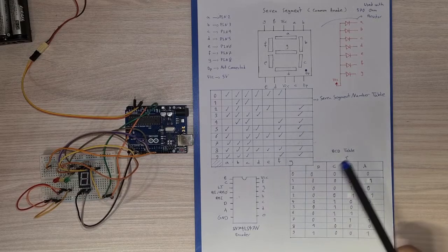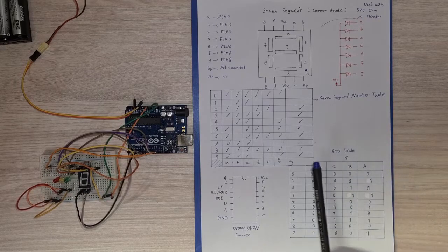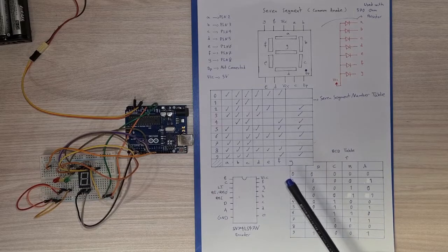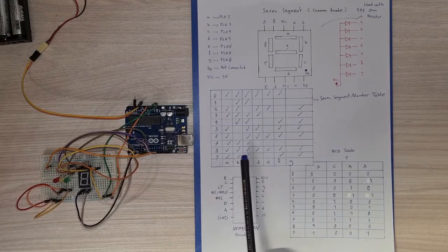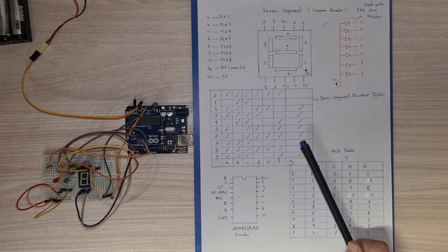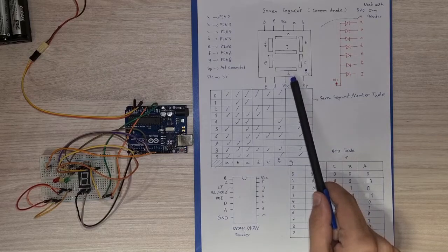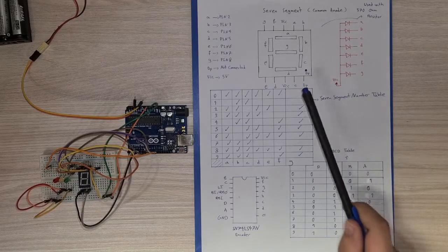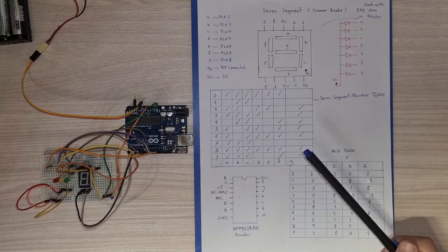Here we have two methods of showing numbers on 7 segment. I'm going for the first one, and in this project I use the first one. So let me explain the first one first. We have a table here, which is the 7 segment number table. For all the numbers that can be shown on the 7 segment, there are 7 pins. So with just controlling these 7 pins on the 7 segment, we can show each number.